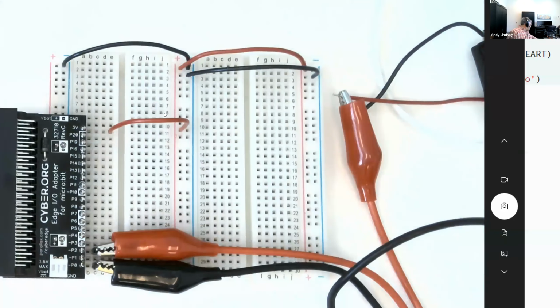And then the red socket, after getting the wires as so, should be connected to the red sockets by the red stripe. Those are all interconnected. And the electrical connections that we've created here are basically giving us this 3 volts of power on the two, the center and the right bus strip.